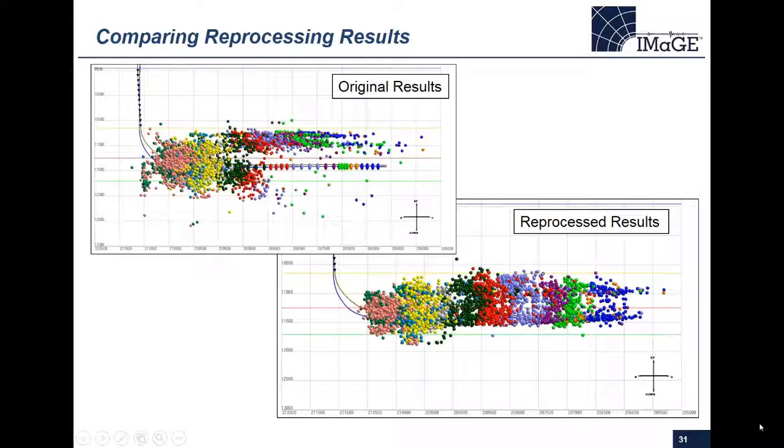And if you were to play one of these stages in time, you would see the events start at the treatment well and grow upwards. So all the early events for the pumping stage occurred down near the treatment zone, and the later events are shallower. So it helps to show that the reprocessed results are likely accurate.